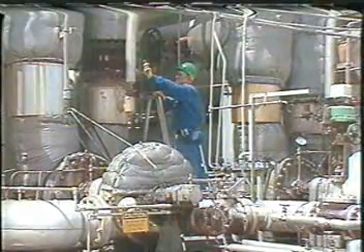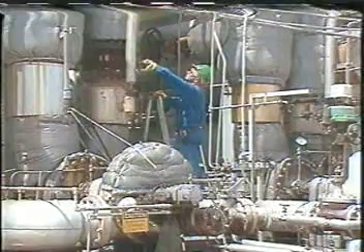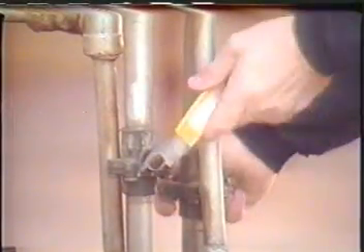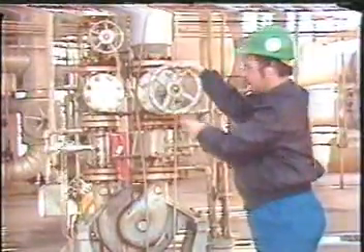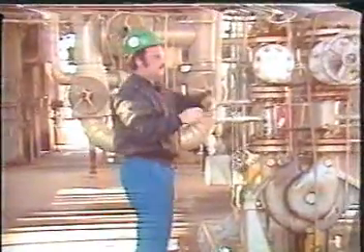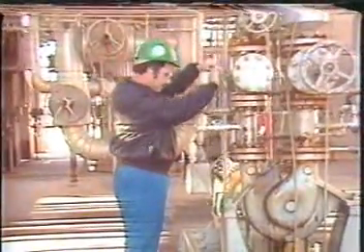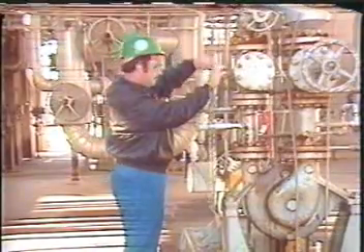If the pump is to be kept at operating temperature, open the warm-up valve and shut off the cooling water supply to the bearings and packing. Finally, close the suction valve and open the drain valve if appropriate. Be sure that the liquid is drained into the proper sewer.